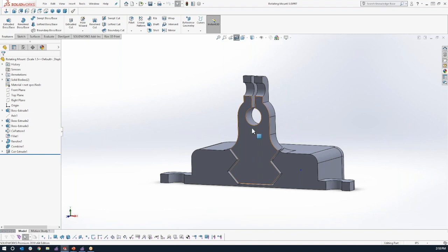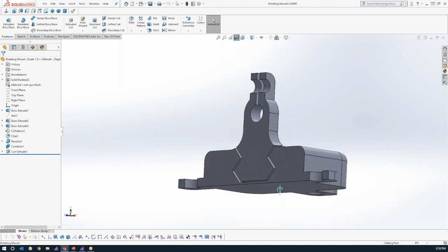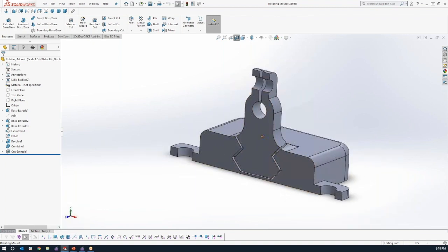to crack this joint and make a moving assembly without both parts needing to be attached to the bottom. So this bottom part will be flat on the bottom and can be fastened to a breadboard or something else, and this top piece will be free to move despite printing them in a single build.